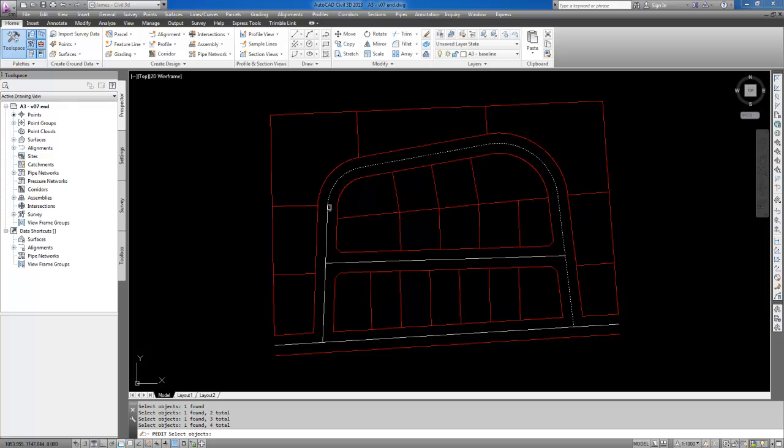As long as the endpoints match, AutoCAD will join the line segments accordingly. Hit enter, and you can tell that it's joined because AutoCAD will say 4 segments added to the polyline. To double check, you can simply click on the object, and you can see one click will highlight everything. This is how to change the lines into polylines.